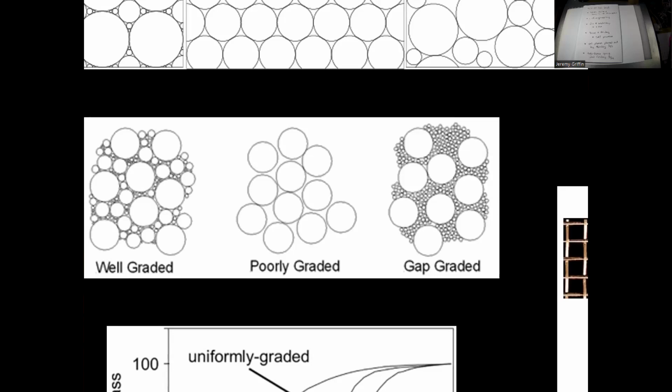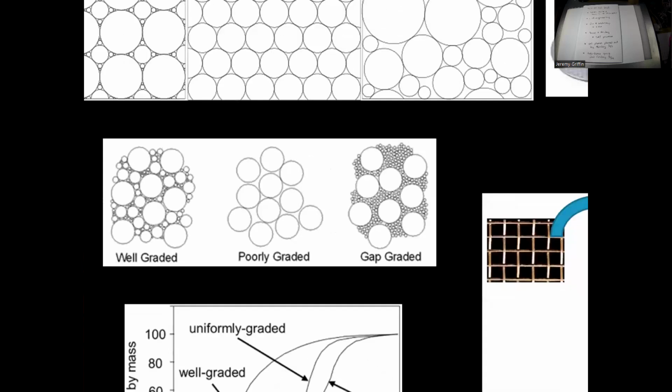So, hey, what if we took some medium-sized aggregate and patched those holes? We just mix in some medium-sized aggregate. But then you guys see where this is going. It's going to be a recursive process where now there's gaps between the medium-sized. Hey, what about some sand or some fine aggregate? So if you want to get the strongest concrete you can, what you really want is well-graded aggregate, well-graded. So you want all different sizes.